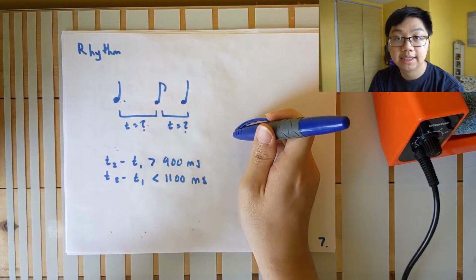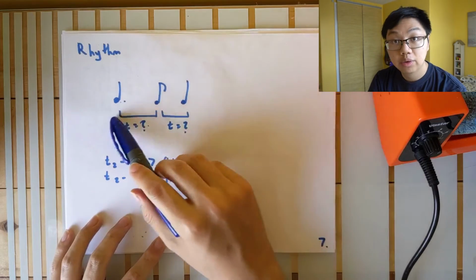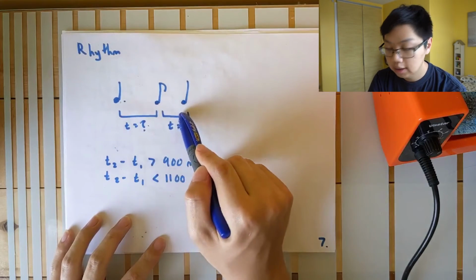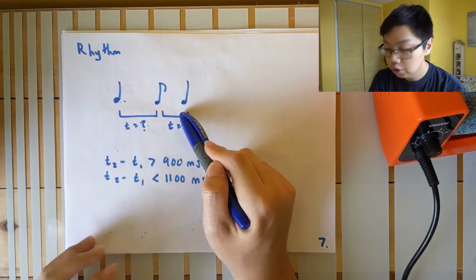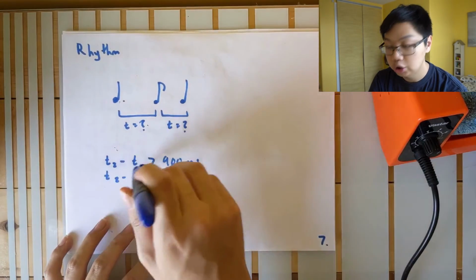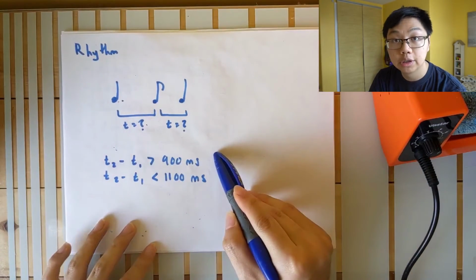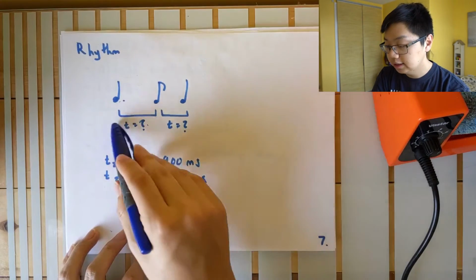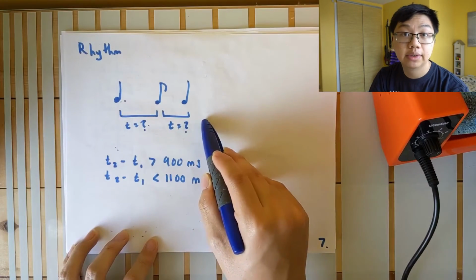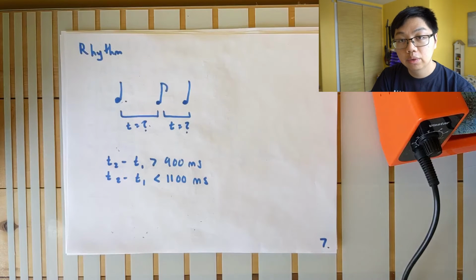The second part is detecting the right rhythm. Depending on the rhythm you choose, the time separating the knocks will differ. Therefore, all you need to do is check to see if the difference between 2 knocks is within a certain time range. You then apply this check to the latest few knocks that have occurred every single time a new knock appears. Playing around with the range is important, because if it's too small, it gets too difficult to get the correct rhythm, and if it's too large, then there are a lot of cases of false triggers.